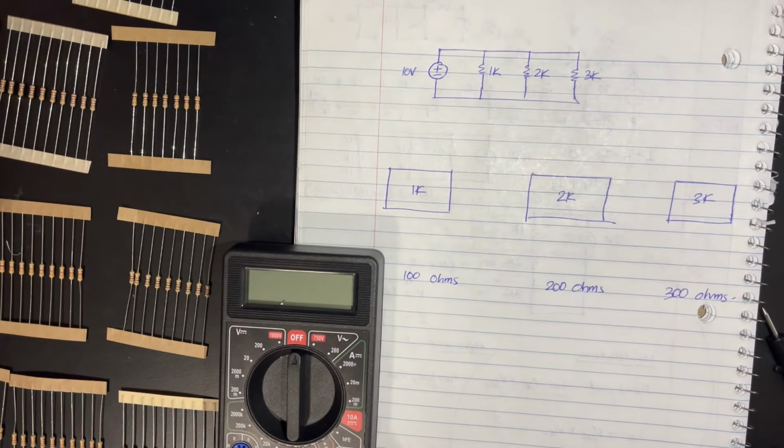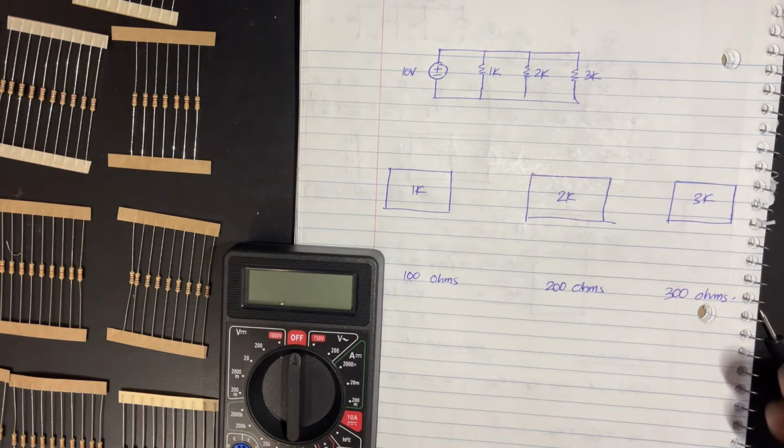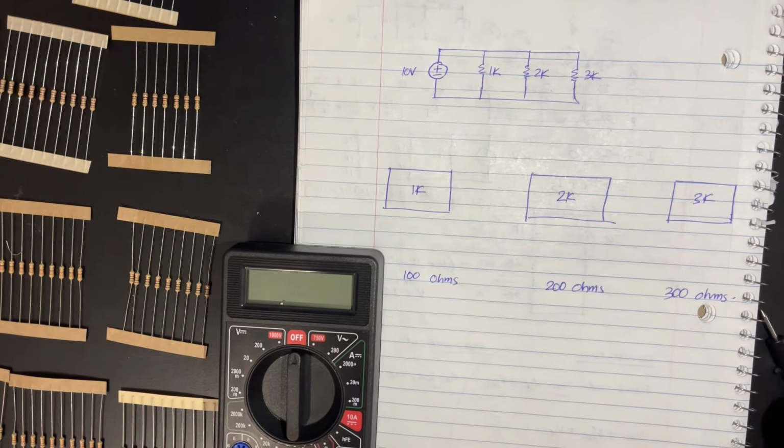All right, so before constructing the circuit, a lot of you have asked me during Lab 0 how you can actually know which one is the 1 kilo ohm resistor or which one is the 100 ohm resistor. Could you please tell me the color code? Guys, let me assure you, nobody memorizes the actual value of a resistance based on the color code. What you have to do is measure it with the help of the multimeter that you have. So how can you do that?